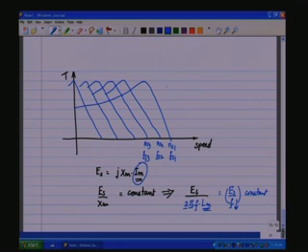And if we have to increase the speed beyond the base frequency, then the voltage cannot increase any further. The voltage has reached its rated. But I can increase the frequency to go beyond this, but if you increase the frequency, the flux decreases. So therefore, beyond a particular point, you will have only field weakening. So I could have a constant flux, constant torque at this point. Beyond a particular point, the field weakens and the torque also reduces.